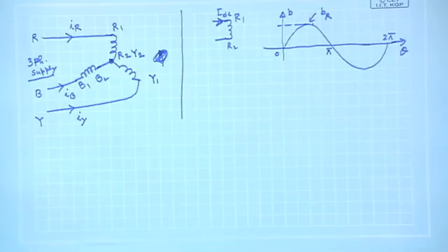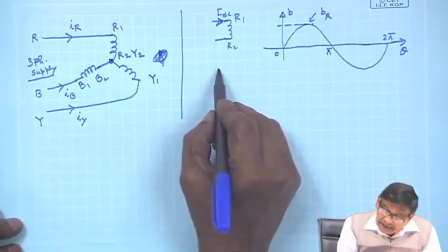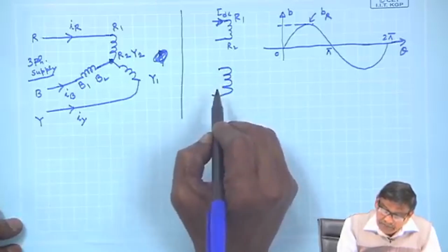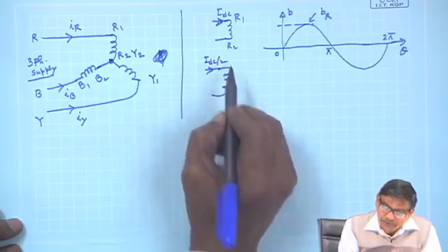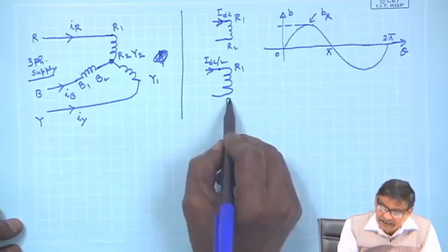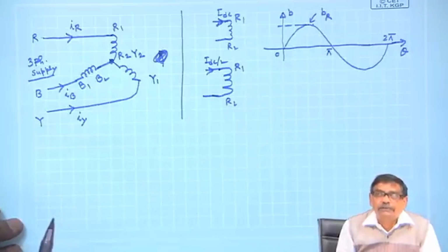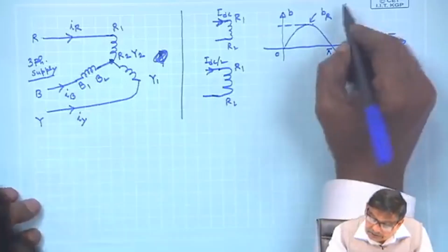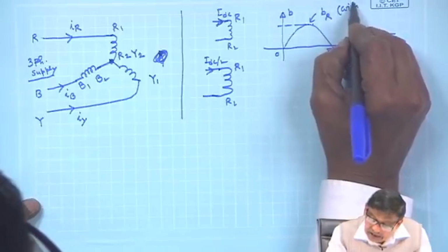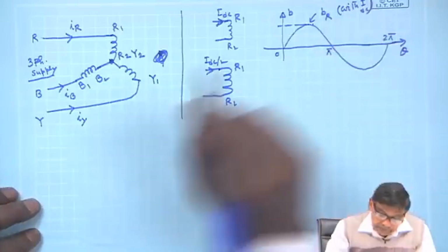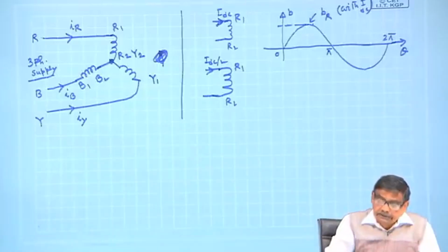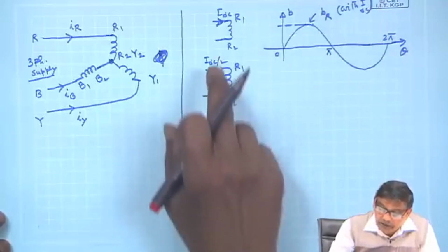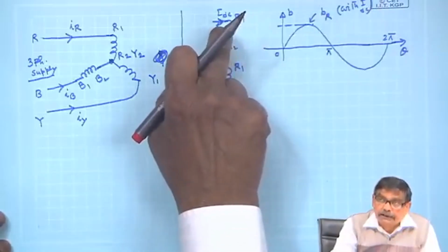What do you think if I say that I will energize the same coil with DC current, but I DC by 2, half, I have made the current half. What will be the flux density distribution? This is with I DC. If you make the current half and if you assume linearity, the maximum value depends upon the number of turns and the magnitude of the current here.